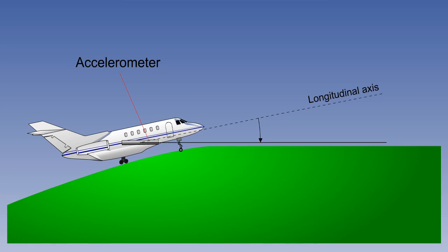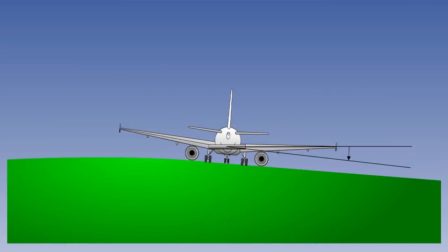With IRS, the accelerometer stays in its fixed position, but the axis transformation system can establish the angle between the accelerometer's axis and the horizontal. The computer remembers this and uses it as the initial datum. The same process is carried out for the initial lateral levelling error.